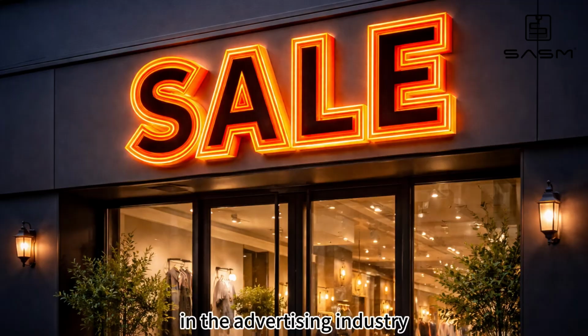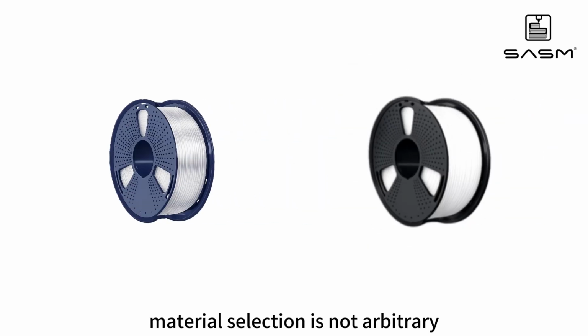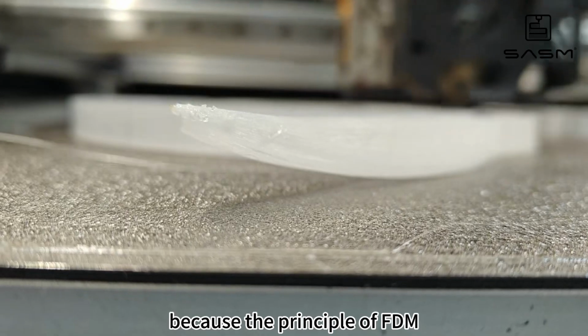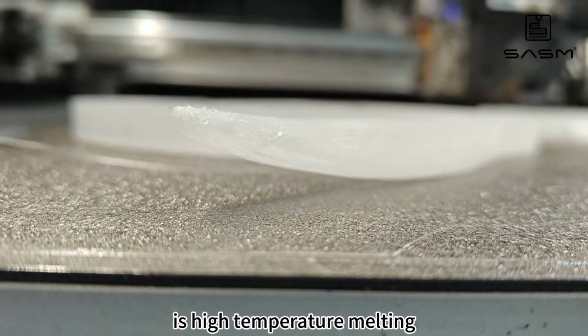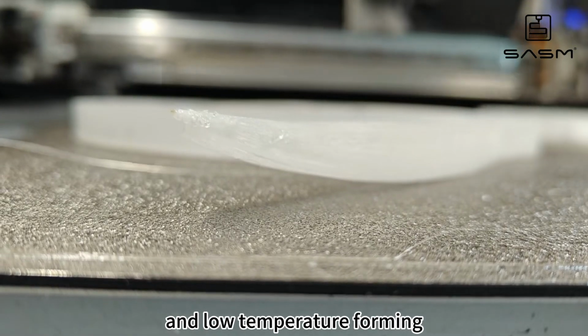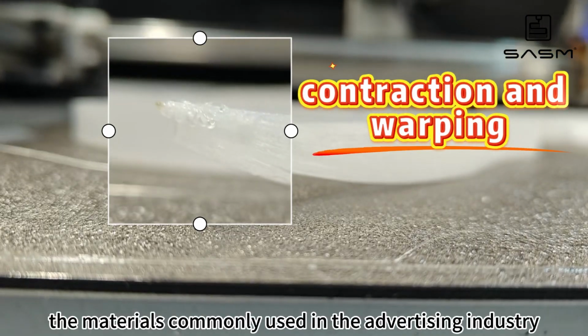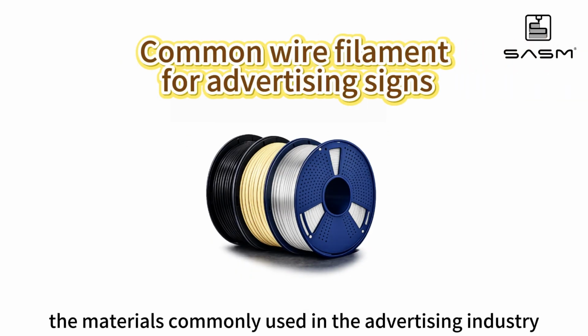In the advertising industry, material selection is not arbitrary, but is determined by the forming process itself. Because the principle of FDM is high temperature melting and low temperature forming, shrinkage is unavoidable and will affect forming quality. The materials commonly used in the advertising industry mainly include 3 types of filament: PLA, PETG, and ASA.